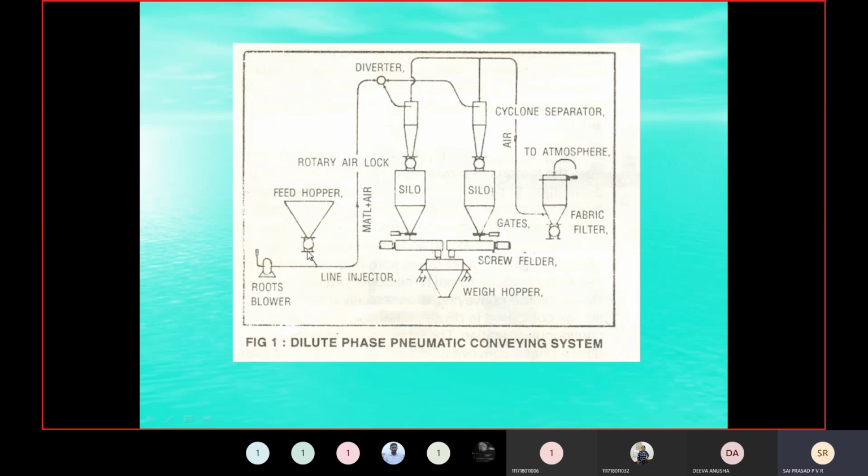To this pipeline we connect the feed. By the Venturi effect, the feed present in the hopper is continuously admitted by means of a feeder. From here, by gravity it falls, and as the solids fall they enter a jet. Instantaneously the solids falling into this line gain momentum because of the moving jet, and they also start moving along with the air.